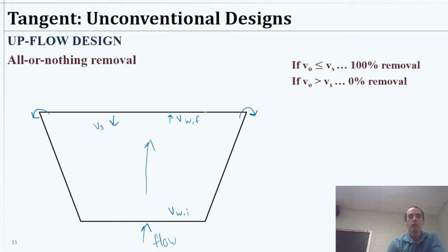So we'll call this one, the V final up here, V naught, because that's our critical sedimentation velocity. We have to at least meet that. The particles have to be falling at least as fast as the water is moving upwards to reach a 0 point, and then maybe they'll hit some other particles and settle faster or something. But generally, anything faster than that will ultimately settle downwards, and at least will not escape over that edge.